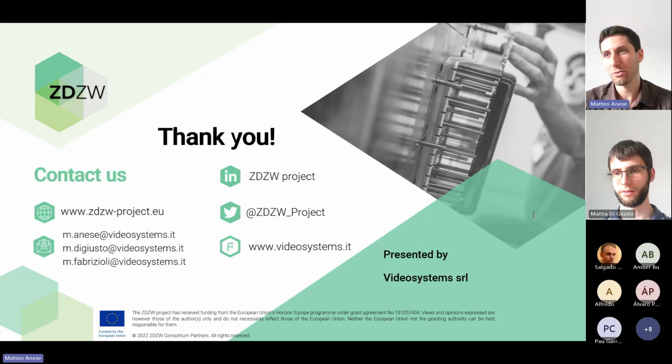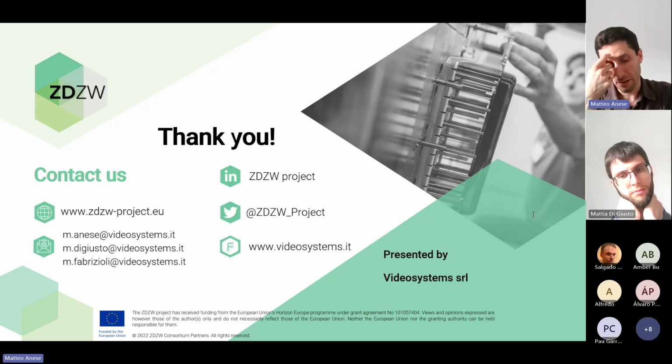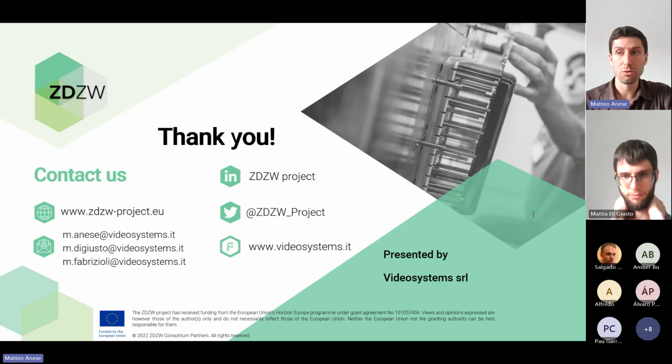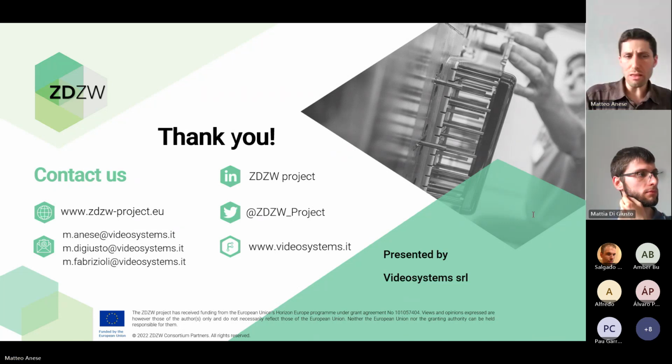It depends very much on the camera used, because if you have a 20 megapixel camera, you can zoom in on the piece and have the desired dimensional accuracy. There is a limitation also. The camera can be put in tight environments, so you can't have the focus, the high resolution, or the illumination required for a nice resolution. So you must balance the application requirements with your capabilities of putting everything inside a box that analyzes the samples in the production line.